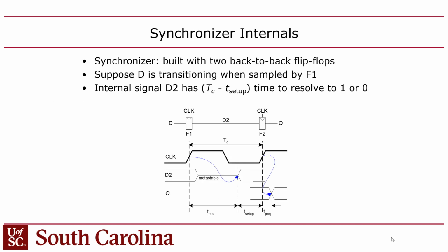Okay, so like I said, that's the synchronizer. It's just basically a dummy flip-flop. So button, dummy flip-flop, and then your real flip-flop that's going to be the input to your design. And then, like I said, after your real flip-flop, you're probably going to have logic there, right? So the whole point of this is to have no logic in between these two guys, right?